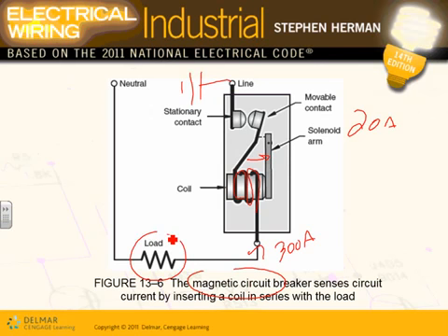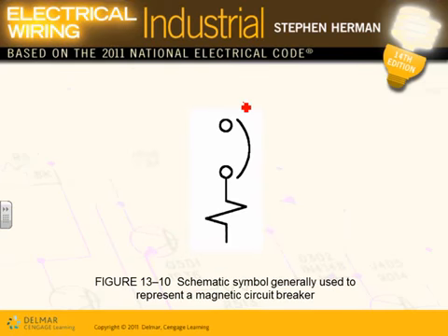So when we say instantaneous trip circuit breaker, this is what they have. In the field, when you guys go, I know one day you'll be specifying circuit breakers, and somebody will say instantaneous trip circuit breaker. What the heck is that? That's a magnetic circuit breaker. It just has magnetic in it. It looks at short circuit, that's all. It doesn't look at overload. And it looks something like this. Okay, so this is the symbol that they use for magnetic circuit breakers or instantaneous circuit breakers that